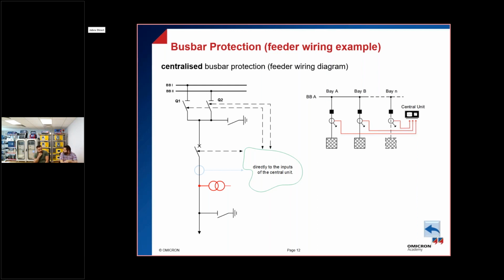Maybe this is the biggest challenge, because it's difficult to have a relay connected to many feeders as the analog input channels are not enough to withstand all. I saw some manufacturers make it in sections like phases, for example one for phase A, one for phase B, one for phase C. Some others have more than one relay, and they consider the overlapping to cover the whole system.